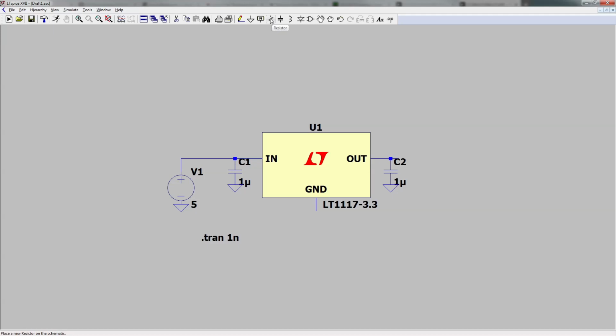Now another way to raise the voltage on the ground pin is with a resistor. Typically voltage regulators have a small current here. This is usually around 5 milliamps, but this is not standard and might vary depending on conditions. So in the end, for sure, the mode with the diodes should have a more stable output. However, the diodes are very sensitive to temperature. So yeah, either way, it is possible to raise the voltage of a fixed voltage regulator.